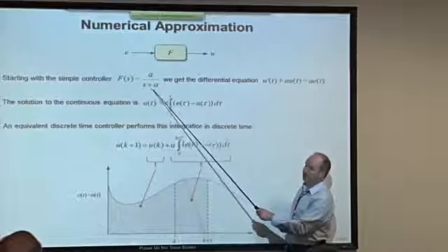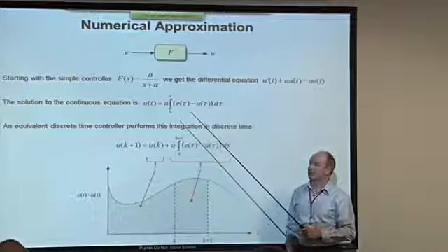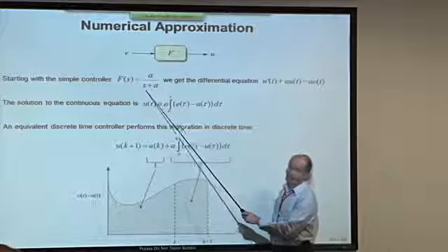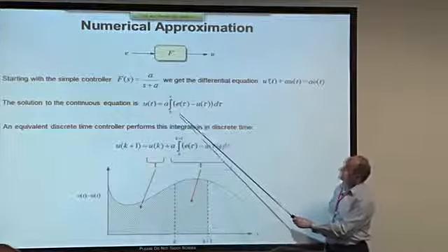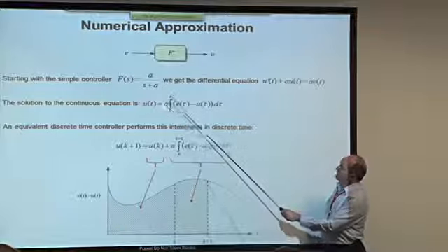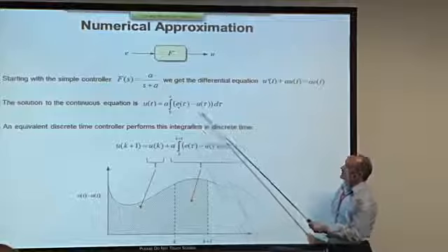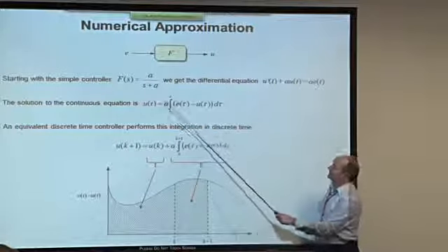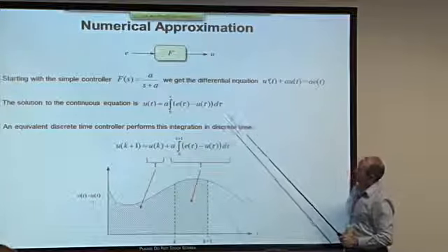A divided by s plus a. So if a is 1 over 2, this is the first-order system that we saw in Chapter 1. Now, in order to find the output of a system like this, we'd have to solve the differential equation on which it's based, and that is an integral. It's a times the integral between 0 and t of this integrand, e minus u, and tau is the dummy variable of integration. This is what you'd have to compute in order to work out u for a given e.